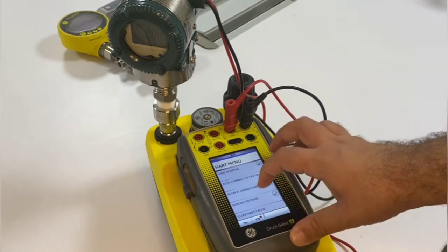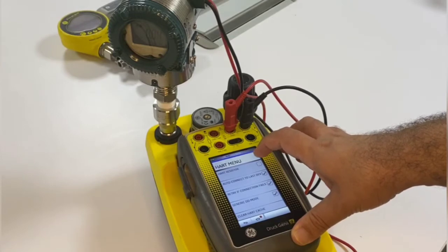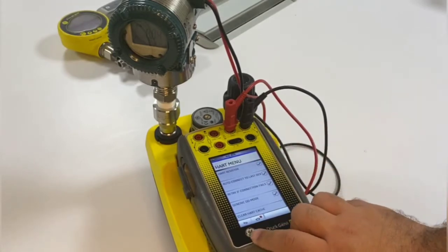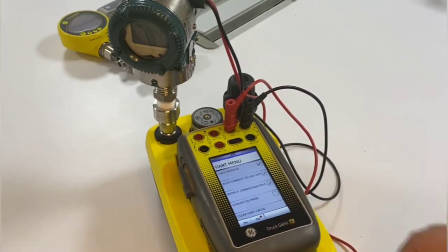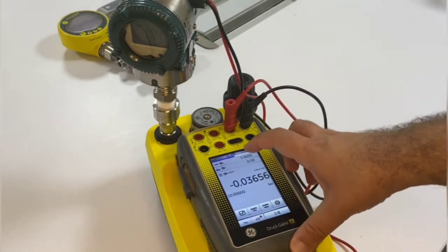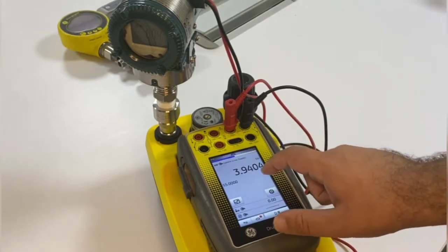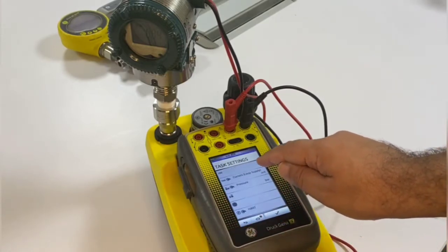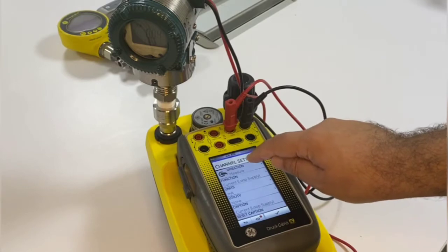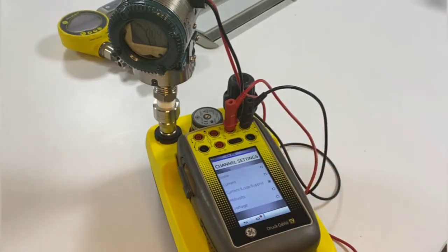Settings: HART resistor, you can add or remove. So here I added the HART resistor. You can use the sophisticated or generic HART mode. The power supply, I already got it from channel 2. So to get a power supply, you need to swipe, go to custom task. On channel 2, you need to select measure of current with a loop supply. So that's what is required.